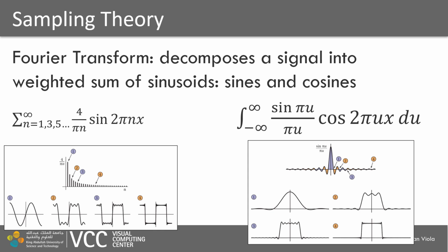where every single signal can be represented by a sum of differently weighted sine waves with different phase and with different frequency. So we basically stack up several sine waves together in order to create an approximation or a full representation of a particular signal in spatial domain. So how does it look like? The Fourier transform could be used if our